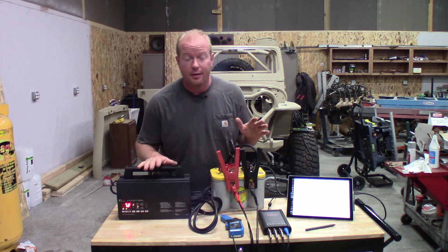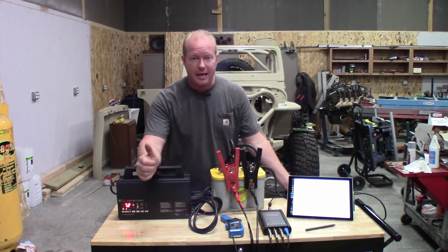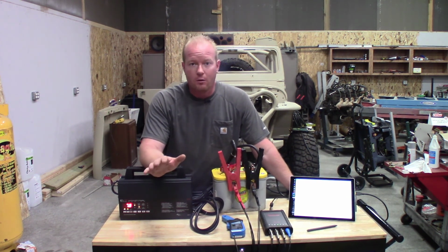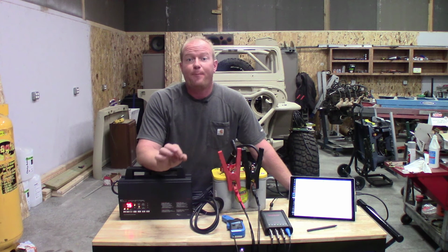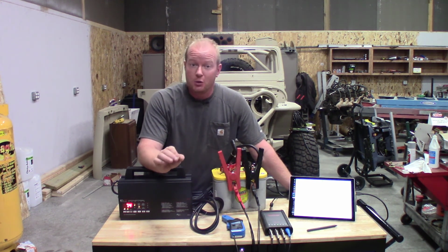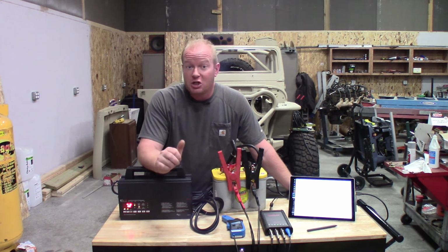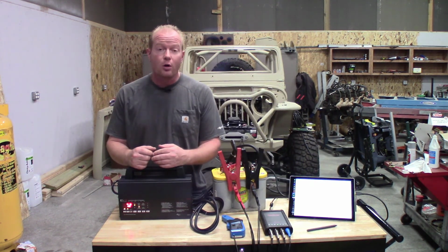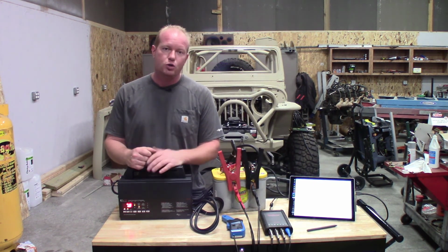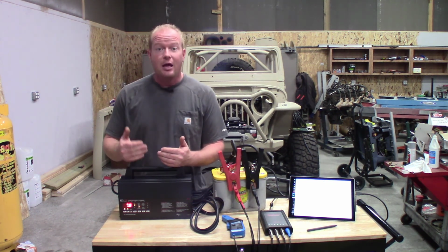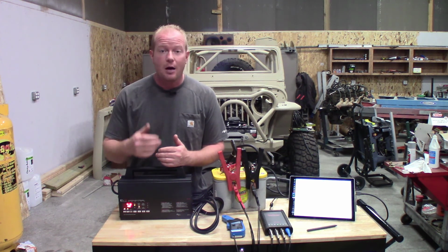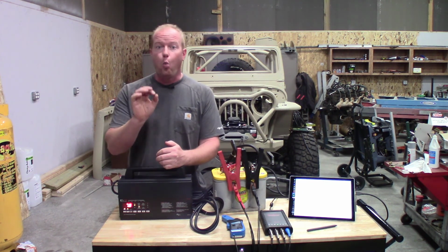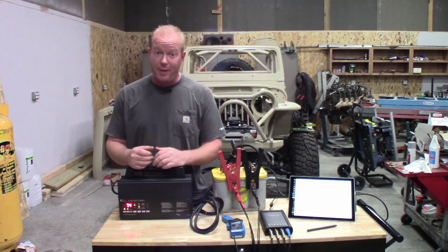So with all that being said, here's the moral of the story. A battery maintainer will not work as a sufficient power supply to program a vehicle with your J2534 box. A battery charger will not work as a suitable power supply to maintain the voltage and amperage required to program with your J2534 device. You need to have some sort of stable power supply to be able to use your J-Box. Now, this particular unit is 70 amps. If you're running a BMW or a Volkswagen programming, you're going to need 100 amps. So make sure that you know what vehicles you're going to program so you can get an adequate power supply.